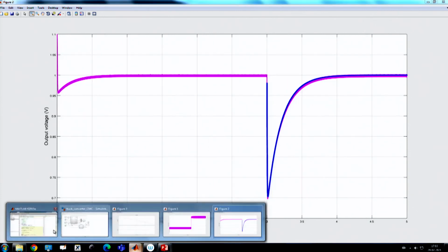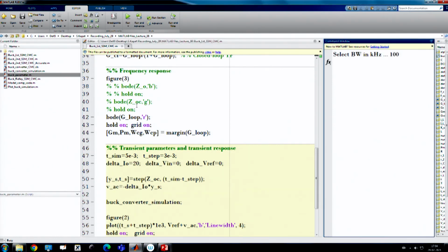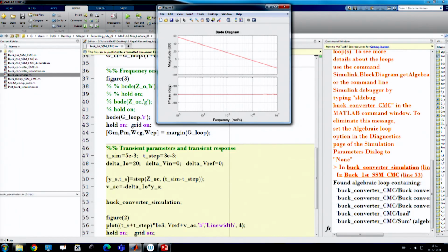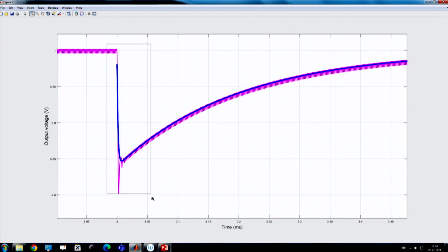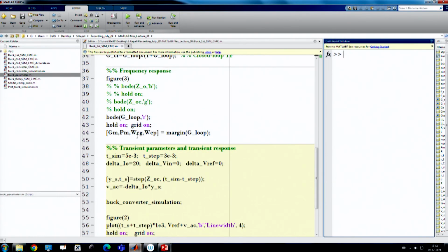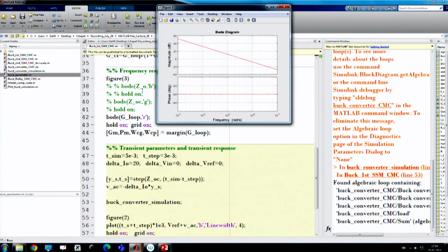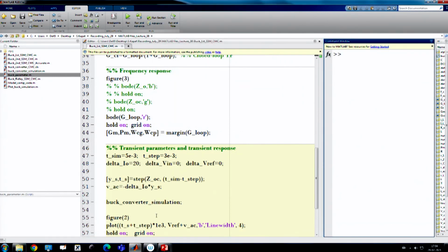Now, if you want to increase the bandwidth, if we again run it, let us say 1/5, that means 100 kilohertz is my crossover frequency, you see the model starts diverging, because in the actual switch simulation you have a huge peak which cannot be captured by your model, because the model will not be valid. So, again I have told that you can select 1/8 as a good number. So, 500 divided by 8 may be a number. That means 1/8 can be a good choice and it matches reasonably well.